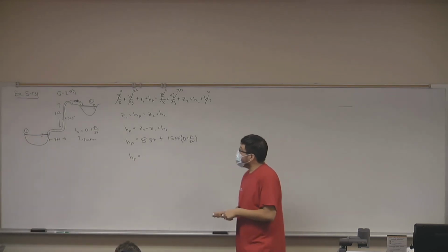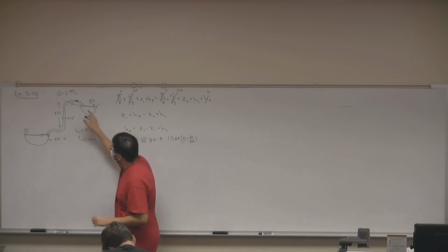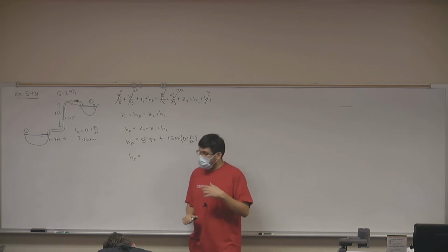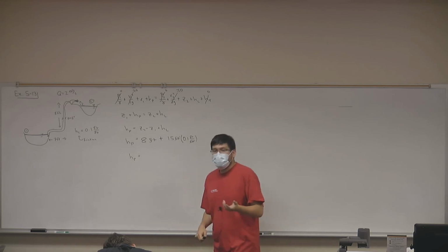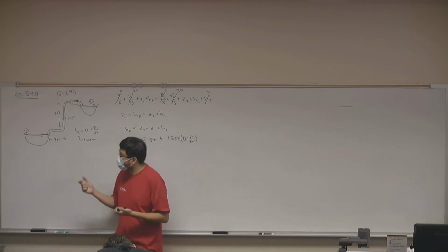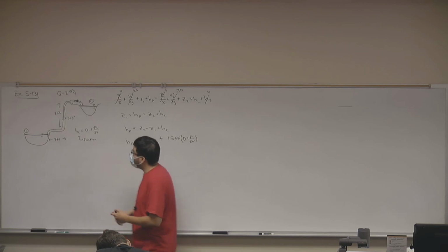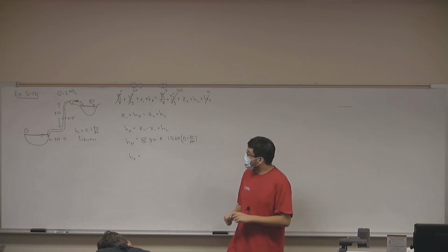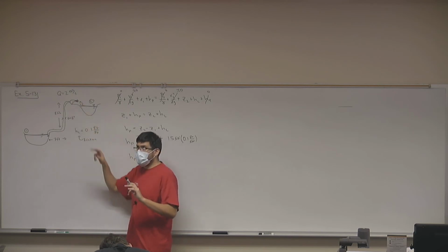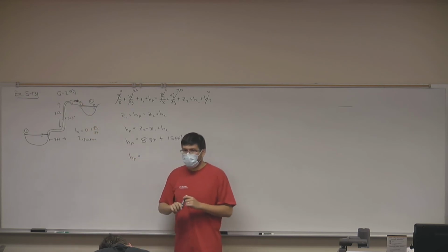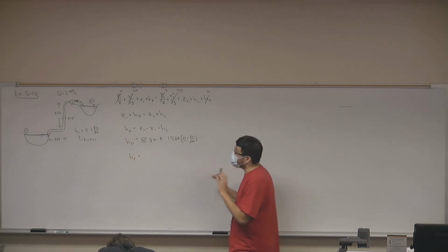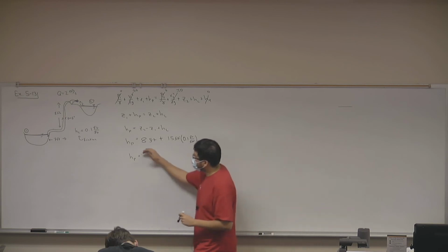The first thing is that while we could assume atmospheric pressure, that is not always the case. In things like wastewater engineering, yes, that will be the case. You design your pipes to have a pressure of 0 at the outlet, but that's not the case for every pumping and piping situation. So I'm going to choose my point at the surface, differing from the book. There are 3 problems where I differ from this book: a stability problem, this problem, and another pump problem.